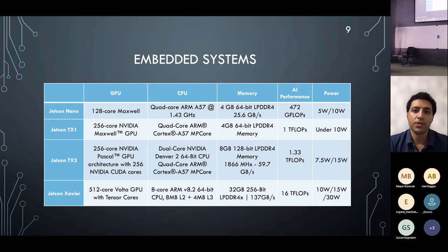Since we are dealing with robots that may be small in size, we should search for embedded systems that are compact in size, low power consuming, and, most importantly, have high computational performance. NVIDIA Jetson devices are embedded AI computing platforms that provide high performance, low power computing support for deep learning and computer vision. We can see in the table a basic comparison between different Jetson modules. Since the Jetson Xavier embedded system is the most powerful among all other candidates, we will use it to benchmark different object detection algorithms to choose the most suitable for our task.